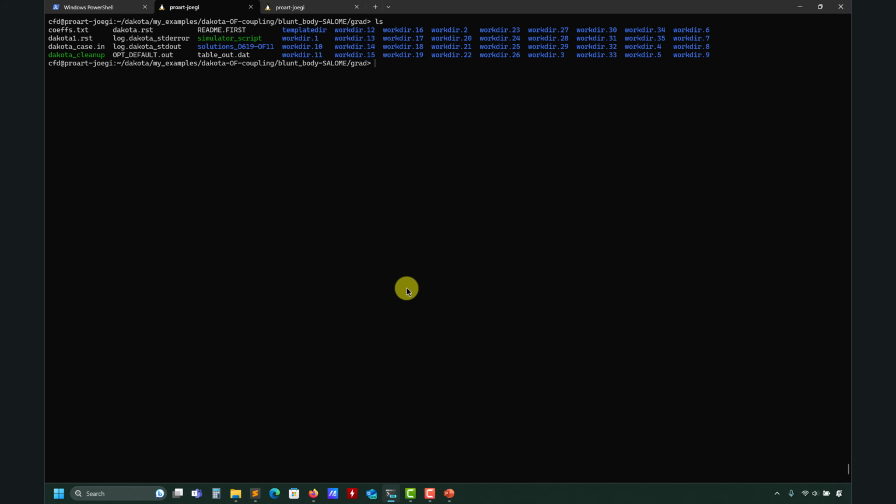Also, there is some practice that some people like to accelerate convergence. They like to map the solution from previous cases to the next one to accelerate the convergence. Depends on the case. Sometimes it can accelerate, sometimes it doesn't help much. So I leave it to you to test that approach. But in my personal experience, you don't gain much, and sometimes you can slow down your convergence, but you need to test it.